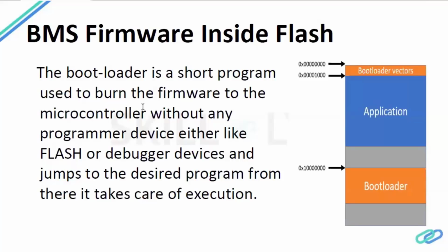One way is to connect your board with a laptop. You have to use some flash software through which you can flash a binary file or SREC file inside the microcontroller. Another way is to have a bootloader. I will be talking about the bootloader in the next slide, but I'm telling you the information now. What is the task of the bootloader?